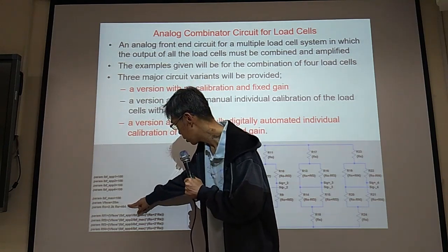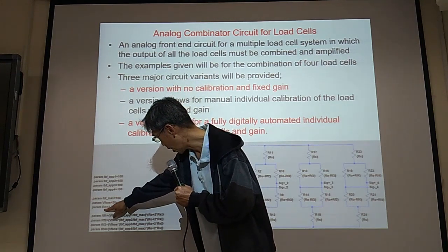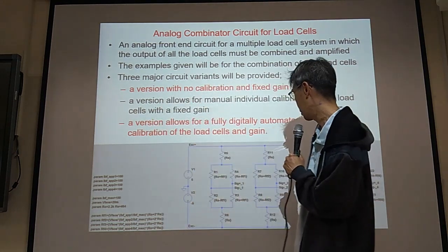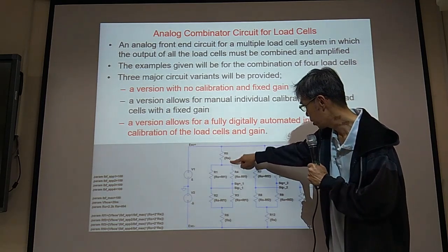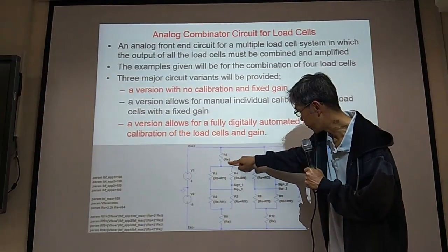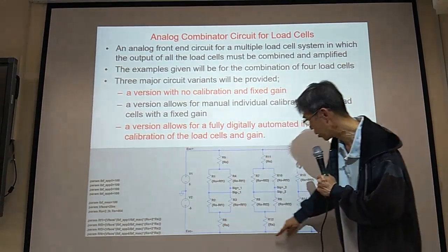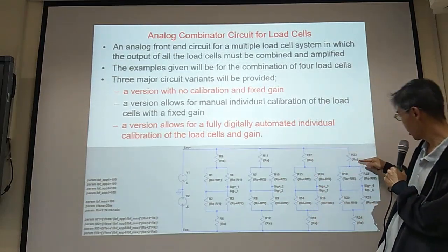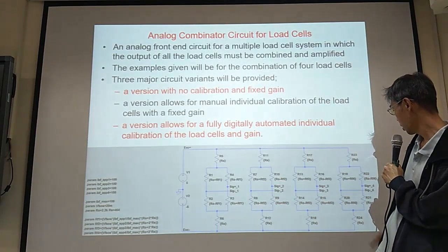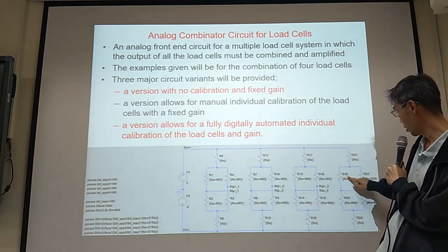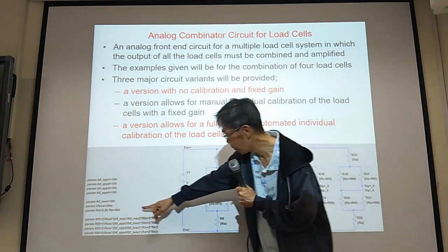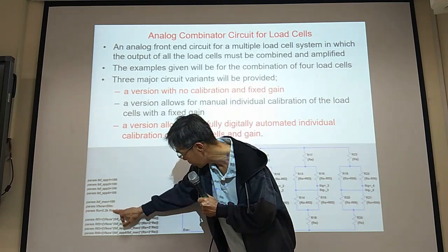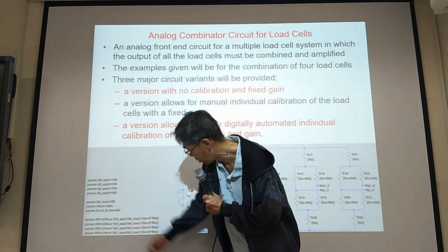Then these are all, and this is R. See, this is compensation resistance, RS, and we have RO, the initial resistance. So for initial resistance 2.2 k ohm, the compensation resistance is 464 ohm.